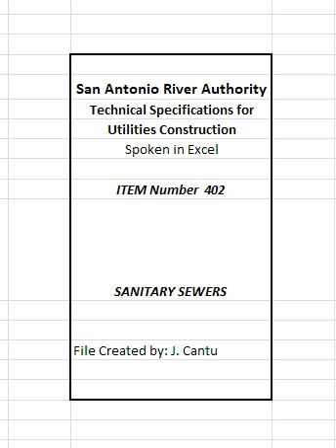C. Working room. The working room for flexible pipe shall be a minimum of 6 inches and a maximum of 12 inches from each side of the pipe to the face of the trench walls. The maximum 12-inch requirement will be waived when the pipe is provided a concrete cover as shown on the standard detail sheet of the plans.